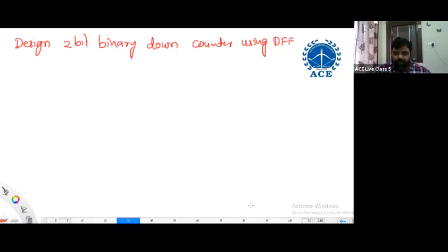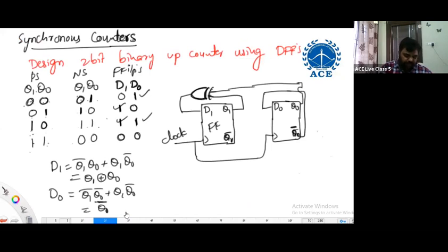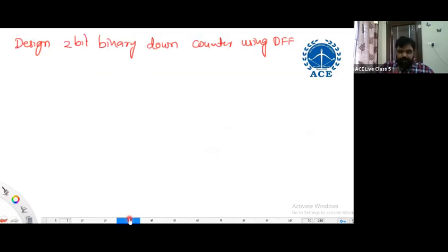Shubham Kumar, we are deriving inputs based on the present state. Present state is not input. While deriving inputs, the combinations we are considering are present states. The input combinations we are considering, correct, but it is not input, it is a state. Based on the state, we are deriving the expected inputs. The inputs are ready, then flip-flops respond to inputs, and we are going to see the expected next state. That is what we need to understand. So the present state we consider as the inputs to derive the flip-flop input expression, but that is not actually an input. It is a state itself.